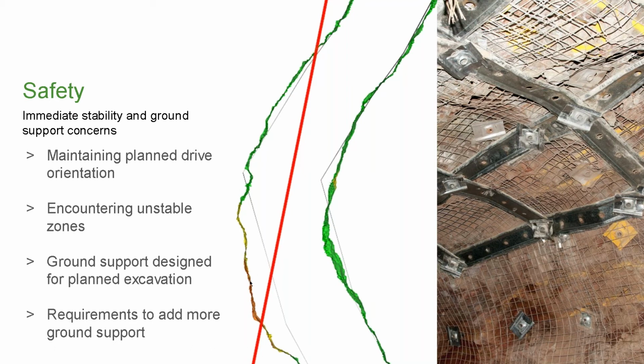In this area, looking at it from a cross-section, we've extended overbreak on the left rib more significantly than on the right. This might require us to add a few more bolts to the pattern, or if the rock really is unstable, have to consider additional ground support measures such as rock mesh or, as seen in the image on the right, straps. This might be something that we can address relatively fluidly through operations, but perhaps it considers further evaluation from engineering or the geotechnical team.